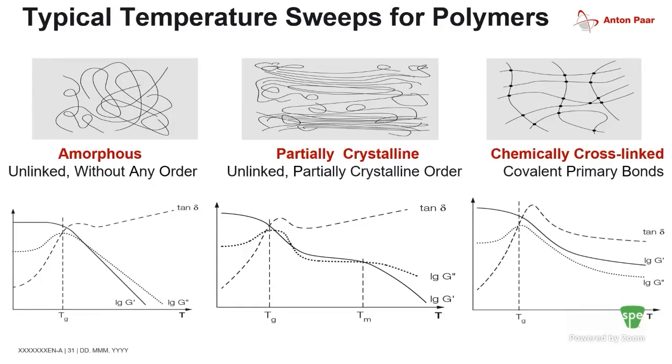Whereas if you have a thermoset or an elastomer, with chemically cross-linked or bonded material, it has a glass transition temperature where it becomes a very rigid material, and then it softens. But we don't see the moduli ever cross, because those cross-linking agents keep it from interlocking or being able to flow or relax. So you have these different behavior responses depending on the material.